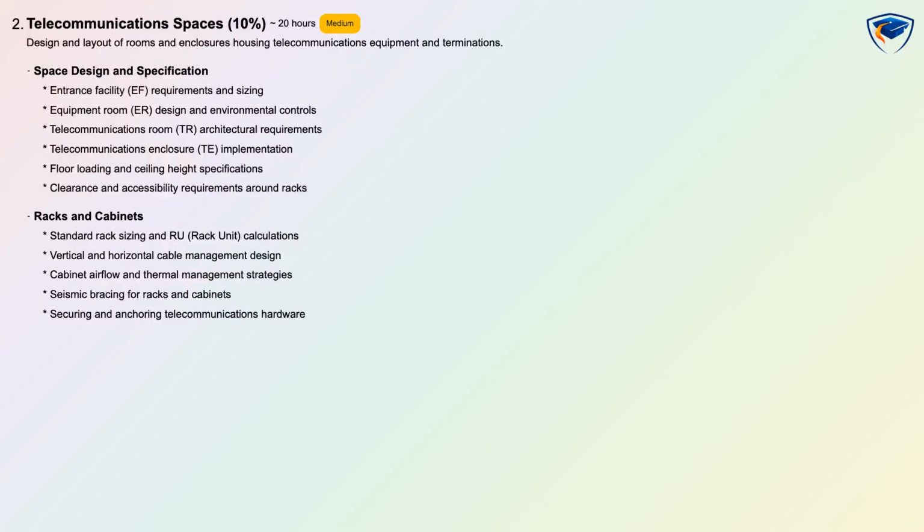Telecommunications spaces is 10%, medium difficulty, and about 20 hours of study. This domain teaches design and layout of entrance facilities, equipment rooms, telecommunications rooms, and enclosures. You will learn sizing, environmental controls, clearance and accessibility, and floor and ceiling requirements that affect equipment placement. Racks and cabinets topics cover RU calculations, cable management, thermal strategies, seismic bracing, and secure anchoring of hardware.